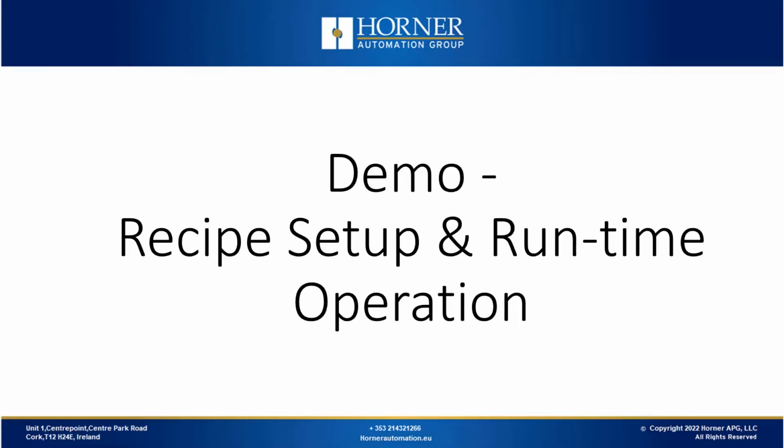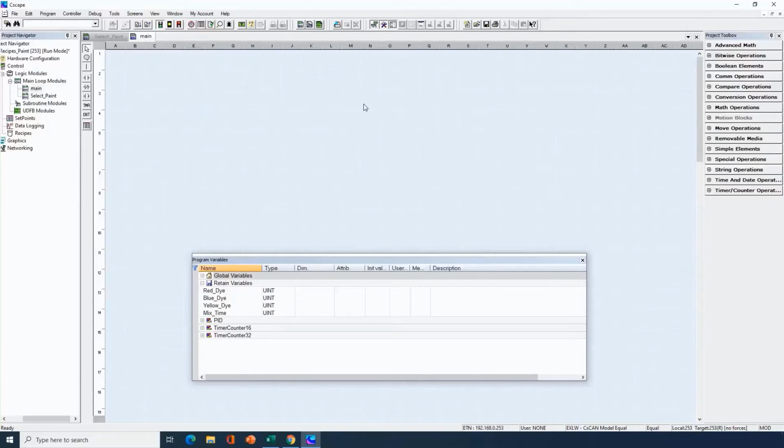Let's begin our demo where I'll be showing how to do that whole workflow process for managing Cscape recipes. So I'll open Cscape. Here I have an application for paint mixing. The first step in our process is making sure we have our process variables created. In this application I have 4 process variables that I'll use as ingredients.